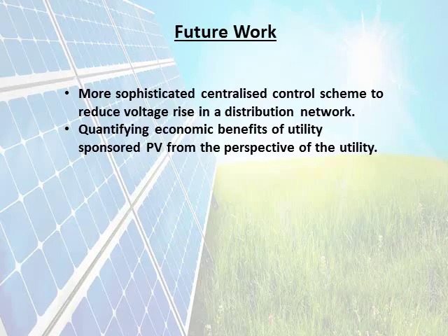Future work for this project includes developing a more sophisticated centralized control scheme that implements 4-quadrant control with the supply of active and reactive power from the inverter, as well as the charging and discharging of the energy storage unit. This control scheme will then be simulated over an entire zone substation, as opposed to one distribution substation.